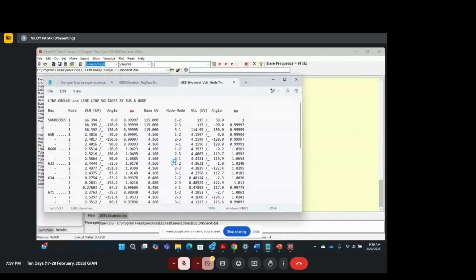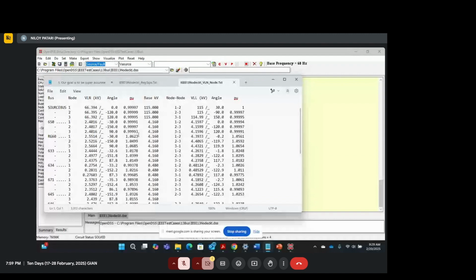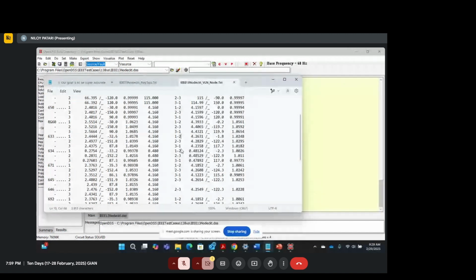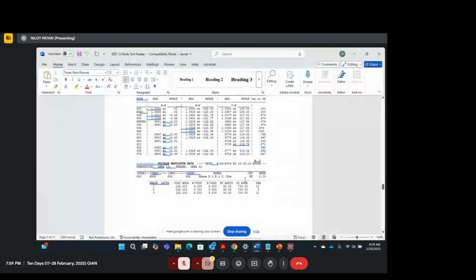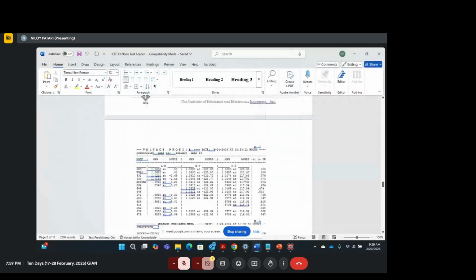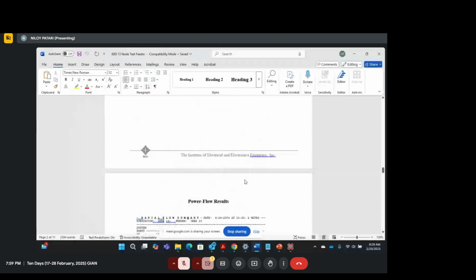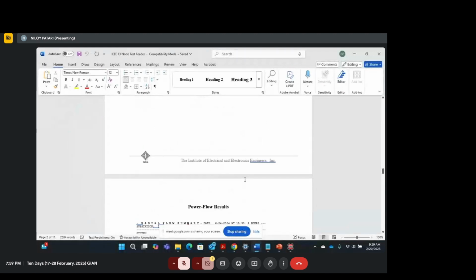You see the voltages had boosted up, right, from 1.0625, but it's not exactly 25, but it's pretty close. Now let's check, say, bus 684 data that you find in OpenDSS, and let's check this one. So at 684.